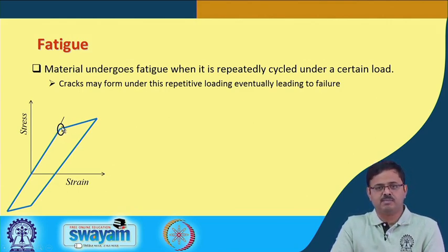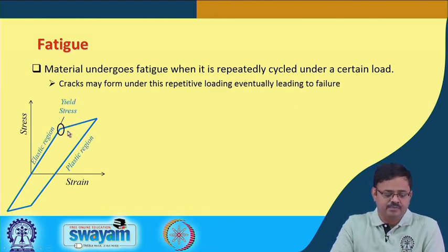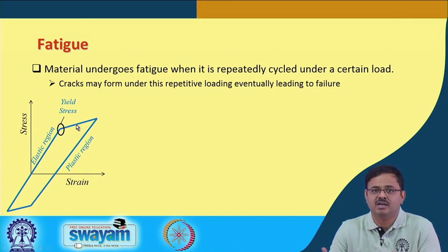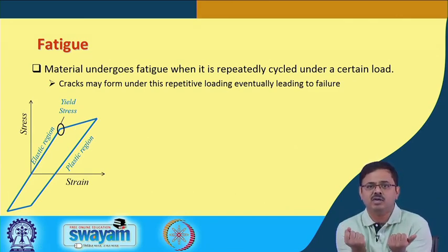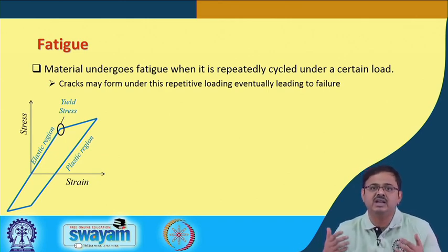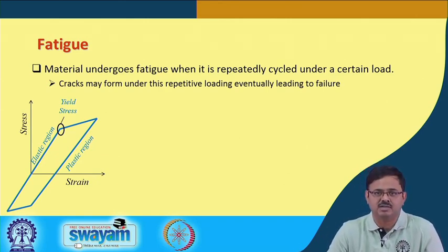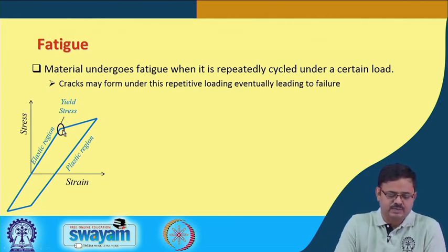We reach something known as the plastic region, right. In the plastic region, it is no longer proportional. In fact, with a little increase in stress, the increase in strain is much more. So, it is kind of yielding. Earlier it was resisting, now I give it a little more load and it says, okay, I give up, I have yielded to the pressure. All right. So, this is known as the yield stress. And the rest of it, this one.